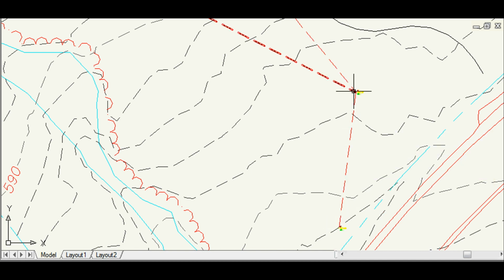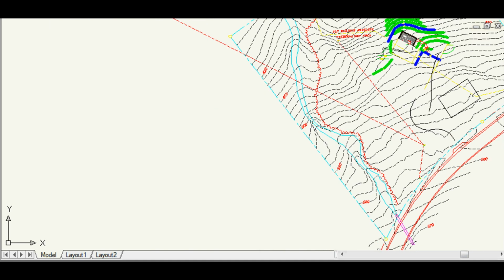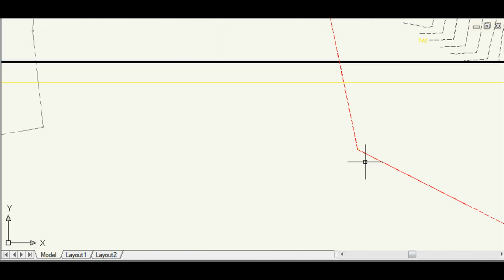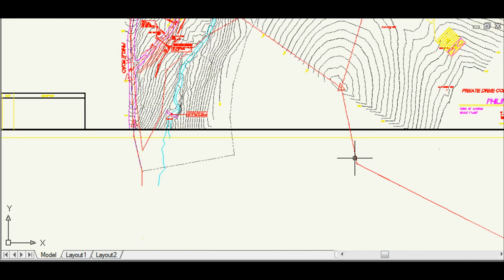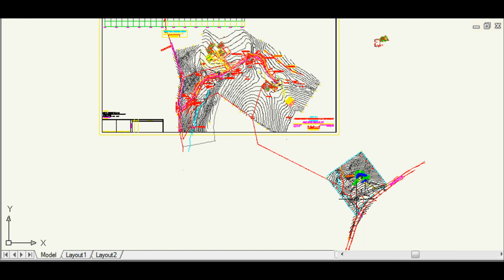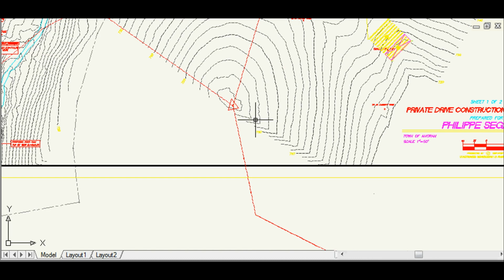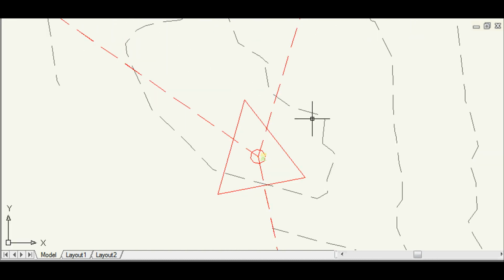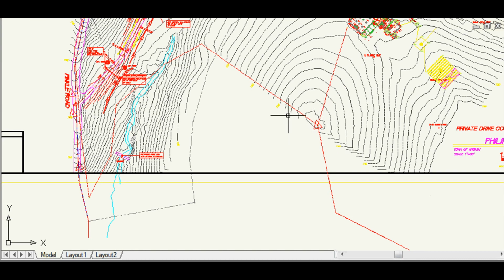Then you set the backside up that was here, up here, and the instrument that was here comes up here, and the foresight that was here goes up here, and you set here, and you turn back, and you measure the distance and angle again to here. And through doing that, you basically build out a locked-in multiple measurement picture of angles and distances of where you're going in the map. And then at each point on the map, with this station, with the instrument, as we stop along the way, along this route, we take our shots.